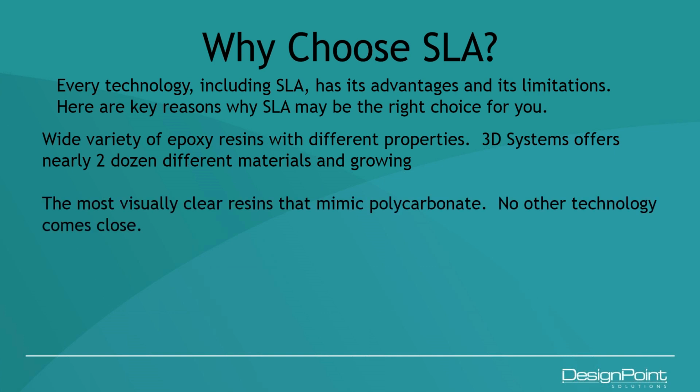One of the big key advantages of SLA technology, and it's very popular in medical devices where they want to be able to see through the part, and popular with companies that are designing glasses, where they'd like to simulate the lens quickly. It has the most visually clear resin that mimics polycarbonate, and from what I've seen and heard, there is nothing that comes that close to such a crystal clear material.